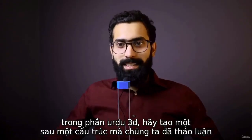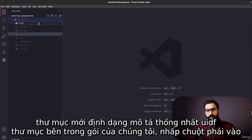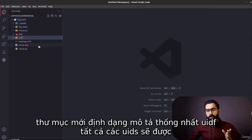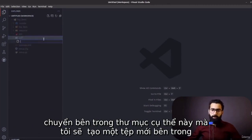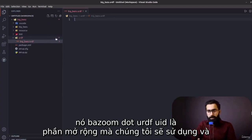Following the structure that we discussed in the URDF theory portion, let's create a folder inside of our package. Right click, new folder, URDF, Unified Robot Description Format. All of the URDFs are going to be carried inside of this specific folder. I'm going to create a new file inside of it, bigbazoo.urdf. URDF is the extension we are going to be using.